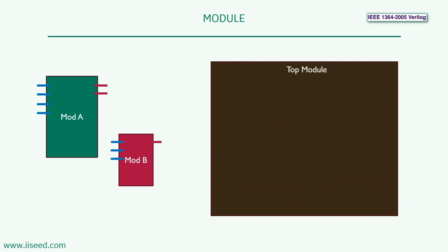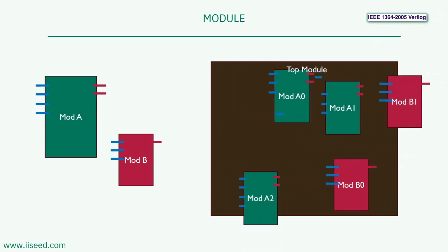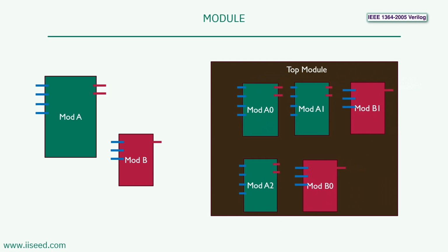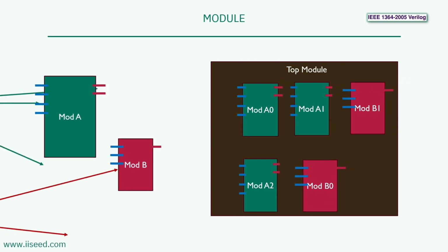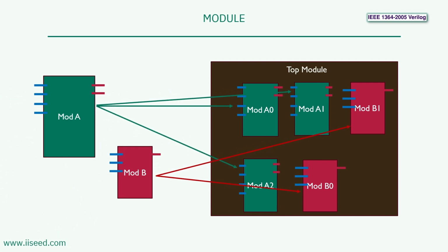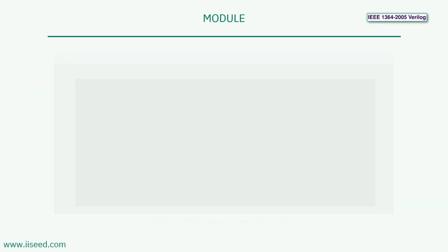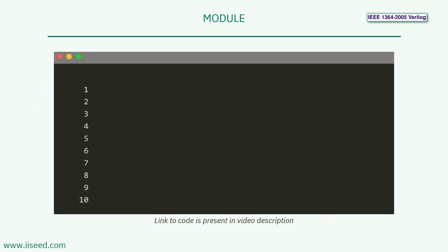Modules have a special reuse ability, where a single module can be instantiated multiple times in other modules. However, unlike classes in object-oriented programming, modules are not dynamic objects at simulation runtime. A module's code is a static template code at simulation runtime. However, there are few ways in which some modifications can be done to the structure of the module at elaboration time, before simulation. Each module can have a set of input and output ports defined as arguments.